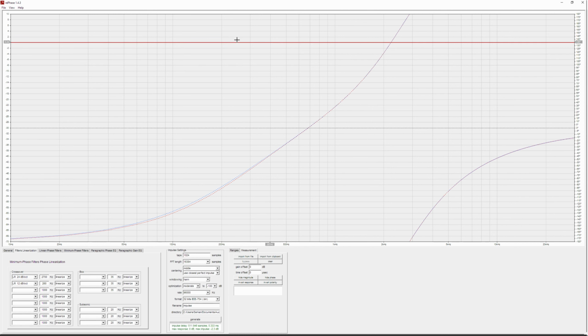As you see, it's now fixed the problems in the frequency response. It is what it needs to be as a phase correction with no effect on frequency response, but it increased the difference between the perfect phase and the phase it will be applying with 1024 taps, but it is still very acceptable actually. In high frequencies, no problem at all, and starting from 500 Hz, just like a 1 degree difference from ideal. It's not a big deal.